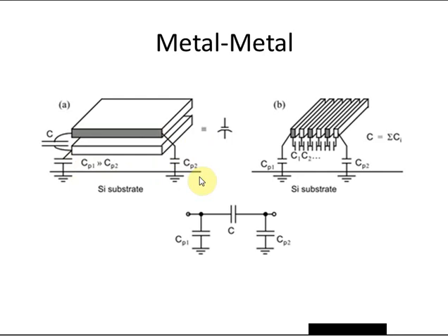Imagine if you're going to be using this capacitor so that one end of it is grounded anyway, connected to a small signal ground anyway. Well, then what you do, imagine this terminal is grounded. Well, you just make sure that this is the bottom plate of the capacitor in the layout. So the fact that it has huge parasitics makes no difference because that plate's grounded anyway. What you're doing then basically is you're having a capacitor where one of the plates has a low parasitic capacitance and you're making sure that that one is on the critical network. This is a very common trick that's used in analog circuit design and very nice and beneficial.